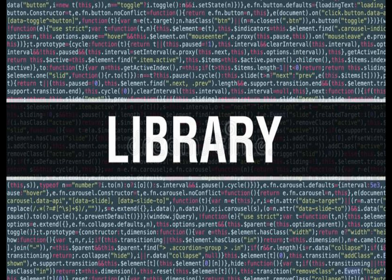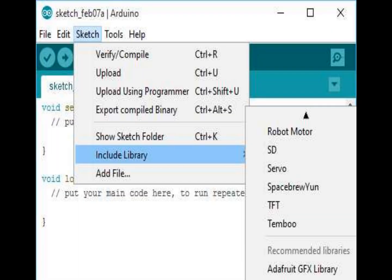In Arduino, much like other leading programming platforms, there are libraries, which are basically storehouses of code that provide immense functionality. These libraries can be imported to enhance Arduino's capabilities and features. These libraries either interact with a specific component of the microcontroller or provide a variety of new functions which can be implemented. But how do you import these libraries? To import a new library, you need to go to Sketch and click the Import Library button. Examples of valuable libraries are Liquid Crystal, DHT Sensor, and NeoPixel.